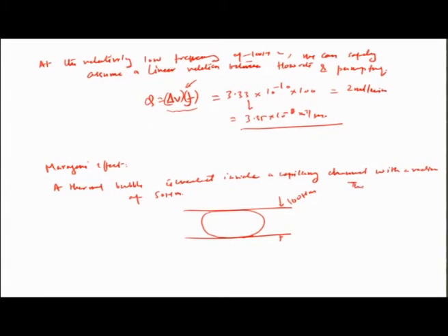and the temperature at both ends of the bubble are 100 degrees Celsius and 50 degrees Celsius. So, let us say there is T2 and T1, this is 100 and this is 50. So, as per the thermocapillary effect, there is going to be a flow of this bubble towards the 100 degree case because of lesser surface tension on the higher temperature side.